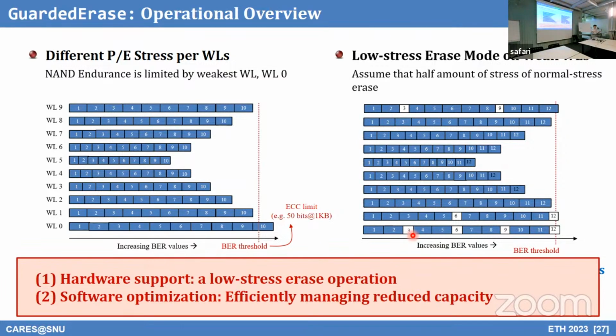By applying low voltage, we cannot remove all the electrons from the charge trap, right? So until the next erase, we are not using that word line. I understand, but can't we verify the voltage threshold in that word line, and then depending on what we want to write... It becomes too difficult, too complicated. Okay. You have to assume this state for particular word line 0 will be 1, and for the other word lines something else. So I think it's doable, but it doesn't make sense.